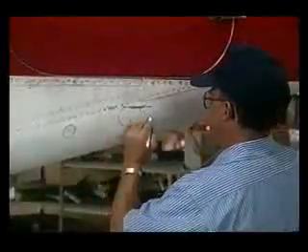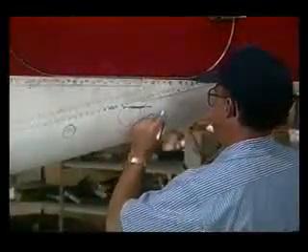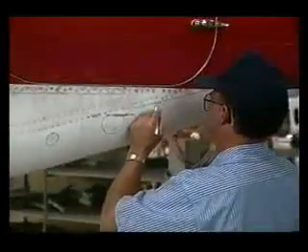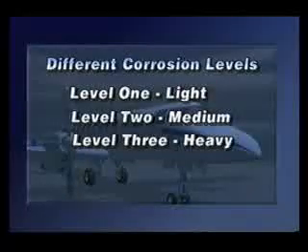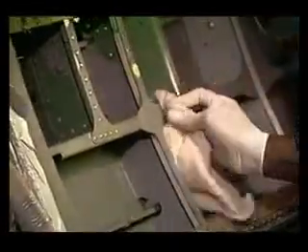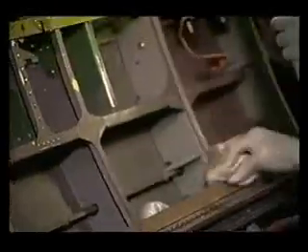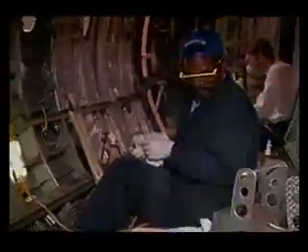To establish a baseline, first inspect the entire aircraft to determine the location of any corroded areas. At the same time, determine the severity of damage. Ideally, the baseline inspection should take place in conjunction with a heavy inspection or aircraft overhaul. This will allow access to all areas which are not accessible at any other time.